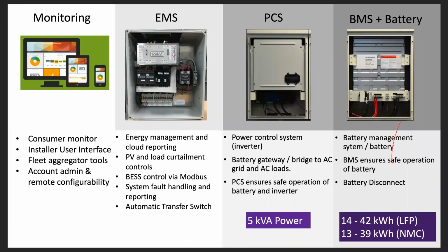Dale's question: is the transfer delay really 4 seconds and not 4 milliseconds? Yes, it is really 4 seconds. It's connected differently if you're used to installing, for example, a line side cap for Tesla systems. The synchronization is different, and the inverter design is different.